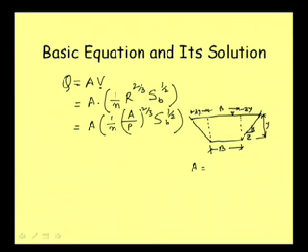Okay. Now normally you will find that we write the area as this plus that, means b plus twice z y divided by 2 into the depth, or we can write this as b plus z y into y.